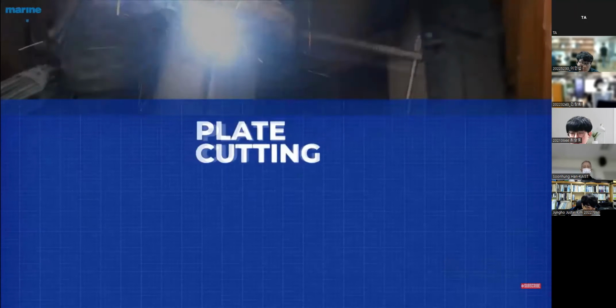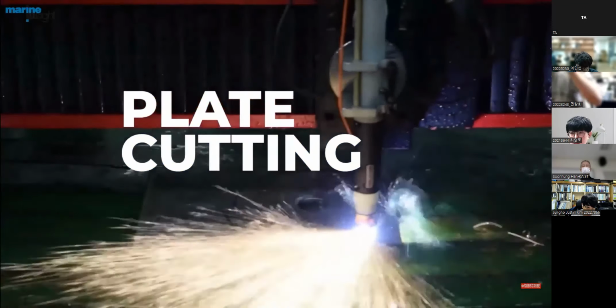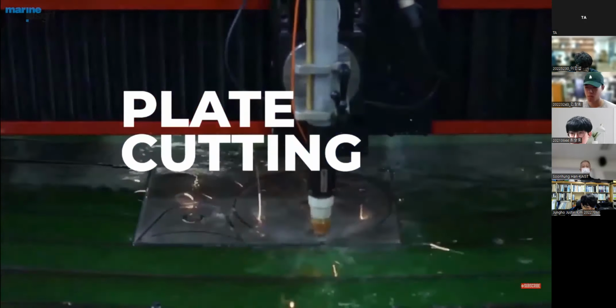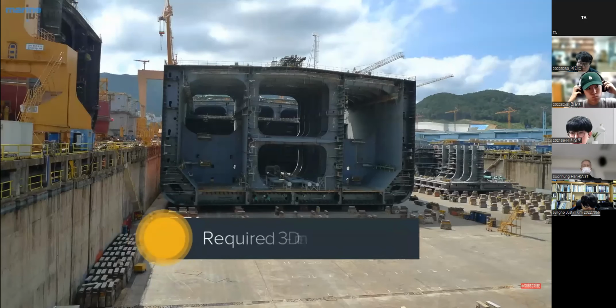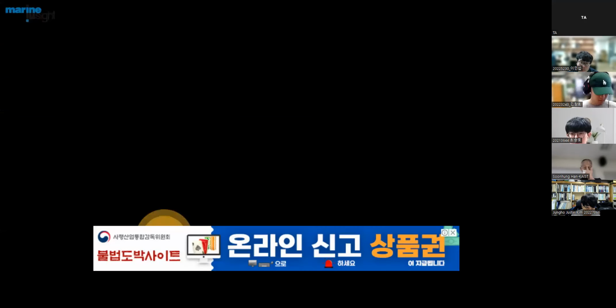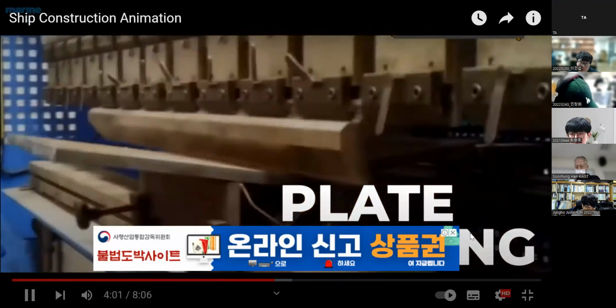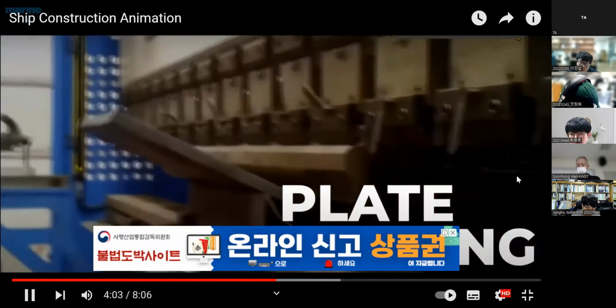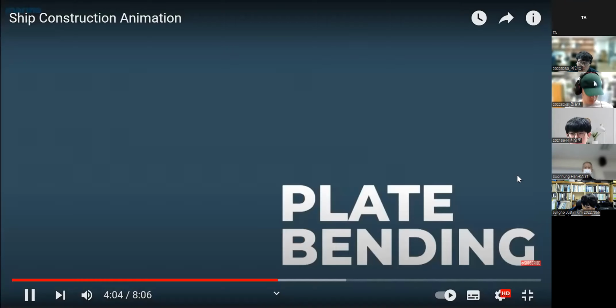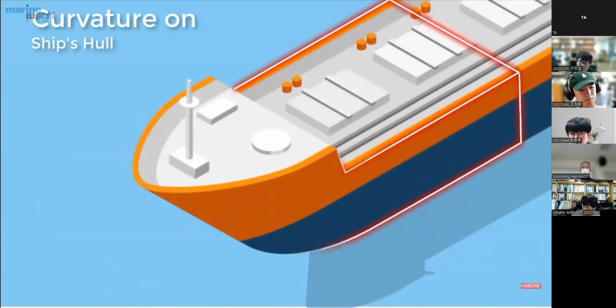Plate cutting. The surface treated plates are to be cut into desired shapes and size in order to be developed to the required three-dimensional shape or used as straight plates for other structural components. Plate bending. A ship's hull usually has multiple curvatures, unless only straight plates are used in the design.